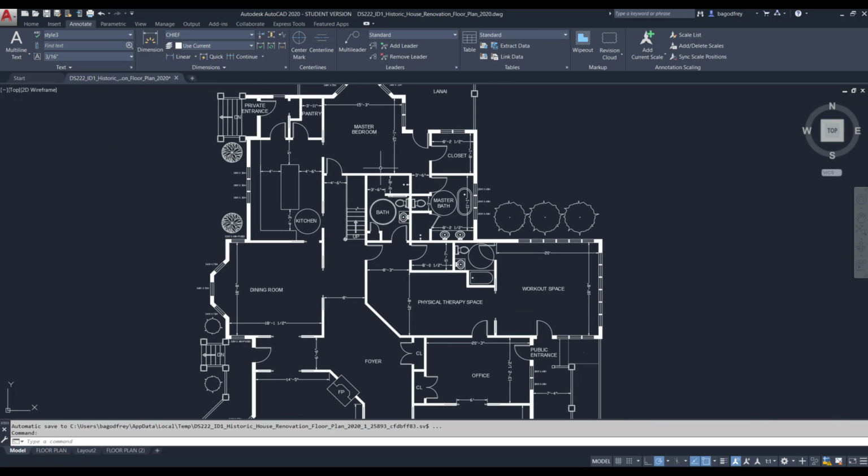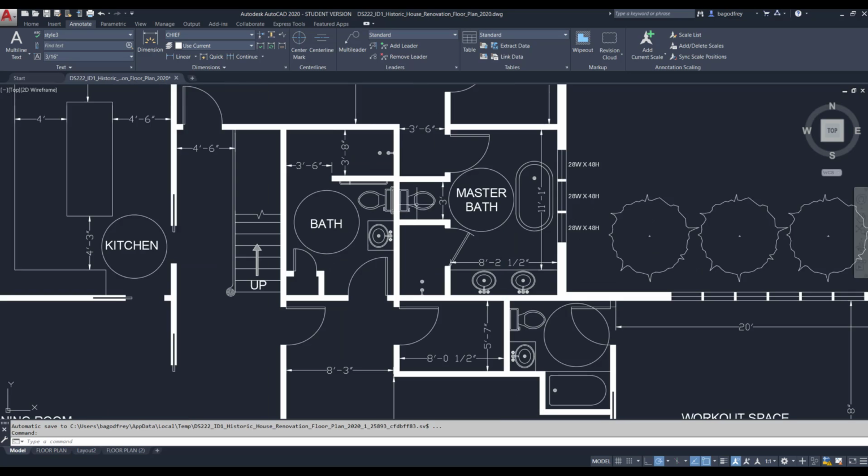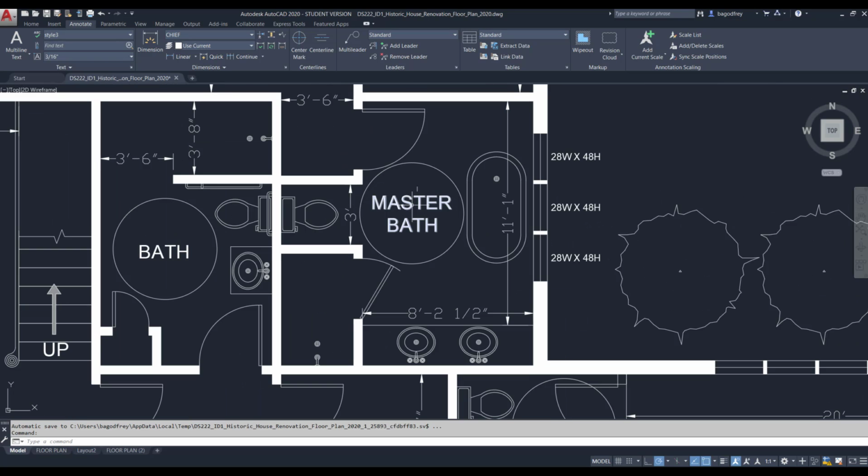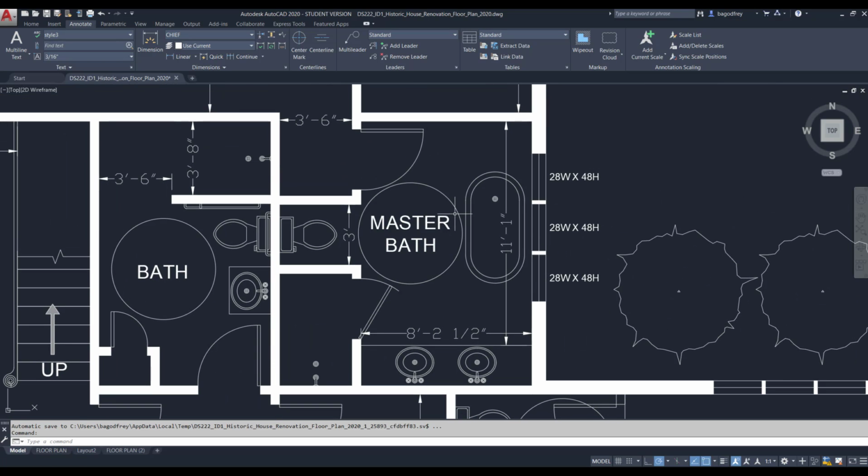Then you'll also be fully developing your kitchen and your bathrooms. We want to make sure we get the important dimensions there as well. So if we take a look at a couple of bathrooms, some things I wanted to point out to make sure you include. So you'll be including the 5-foot turning radius, our 60-inch circle, right? That shows, in the ADA compliant bathrooms, that's possible.